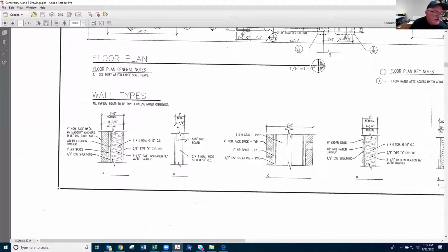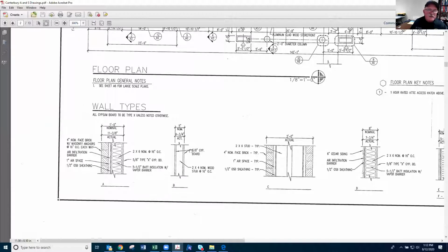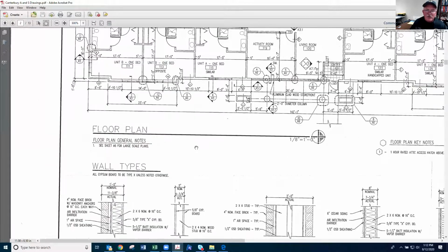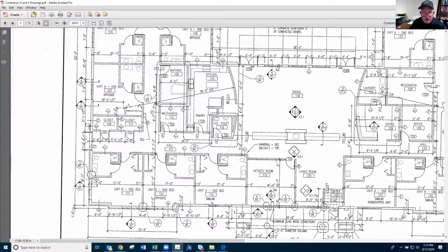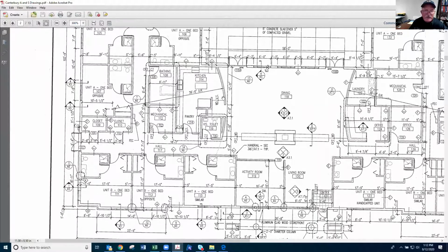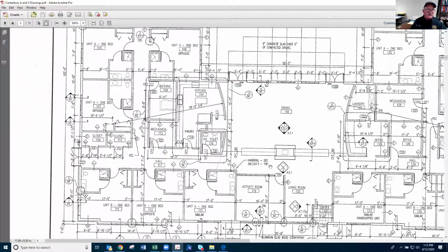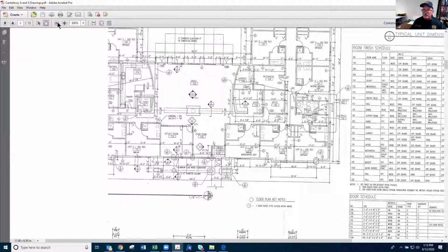If you look at this, it tells you how that firewall is supposed to be installed, where it's supposed to be installed, and the like. Up here is where we find these firewalls. And in fact, I told you guys a while ago, these are firewalls right here. This is a firewall partition right here, okay? So as we look at it and we look at the schedules, we can see the difference. Everybody with me on page 2, how we found that? And you'll be able to find that when you start looking at your own there too.